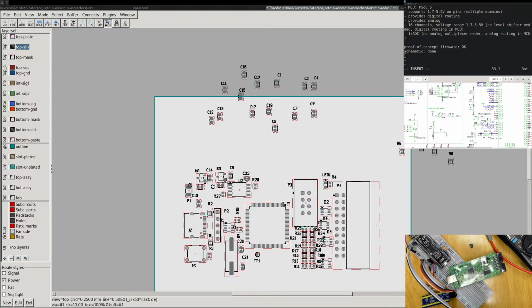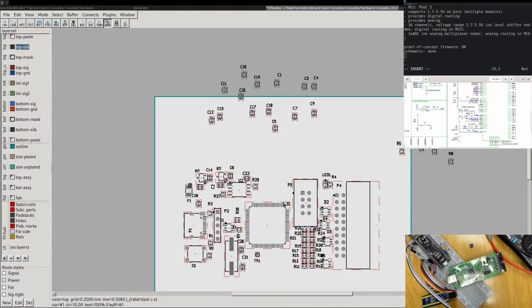And there's a resistor which is missing. Yes, there is. The one which pulls. Yeah, the schematic is not complete. The one which pulls should be connected to the output here with a resistor, so it can actually pull. There's one resistor missing here, and one K resistor.